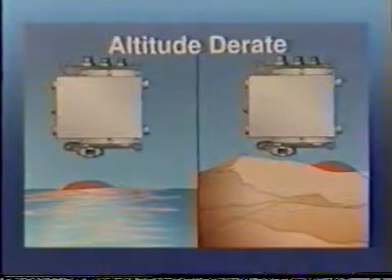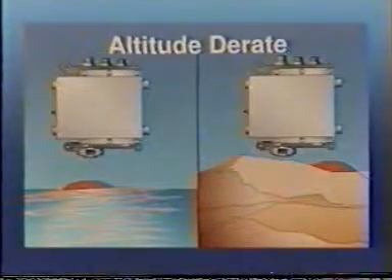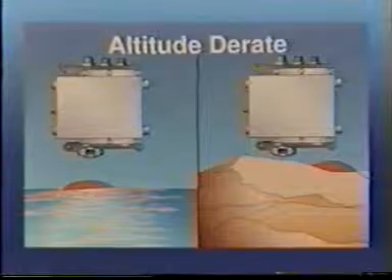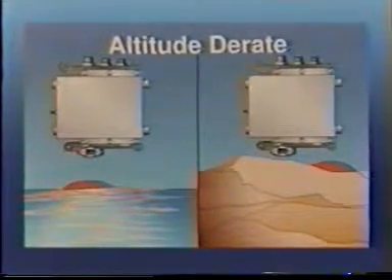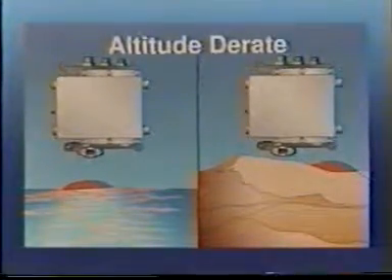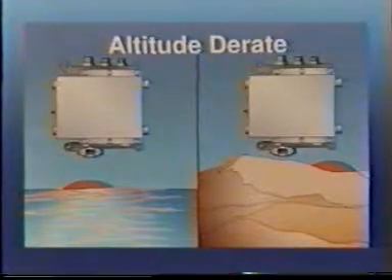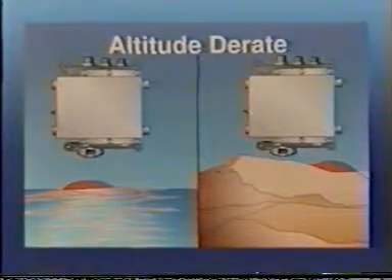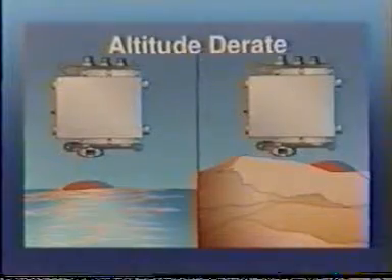The QSK19 fuel system will automatically derate the engine at a predetermined altitude. The ECM determines altitude by monitoring ambient air pressure and, using calibration tables, determines the altitude derate.